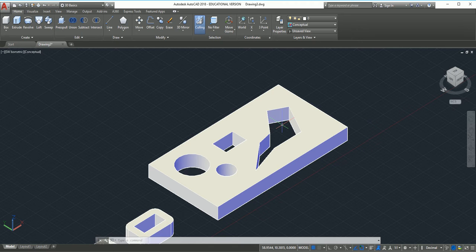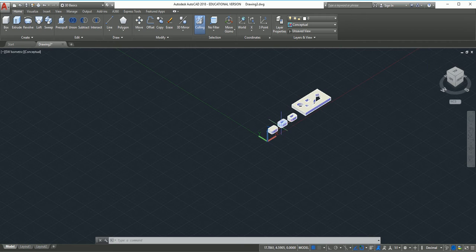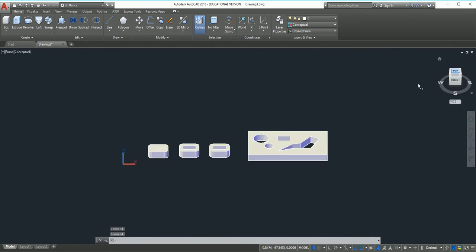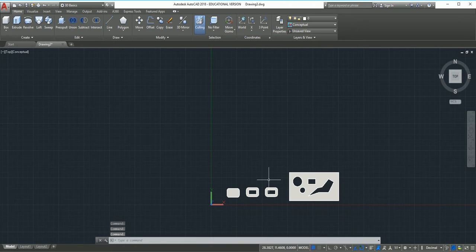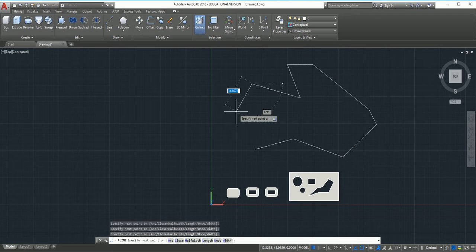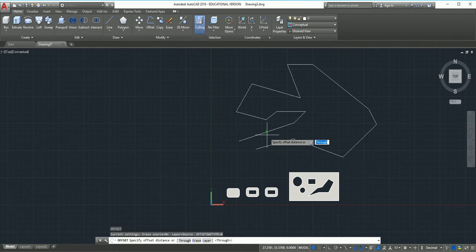Yeah, I mean, and the extrude tool worked the same. So to extrude anything, you're gonna need a polyline, not a series of lines. So where is that? Polyline. I see 3D polyline. PL. No, just type in PL.